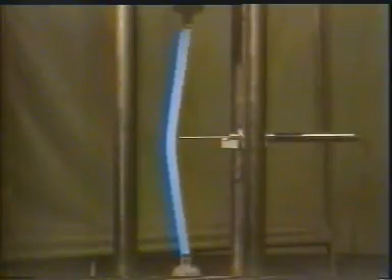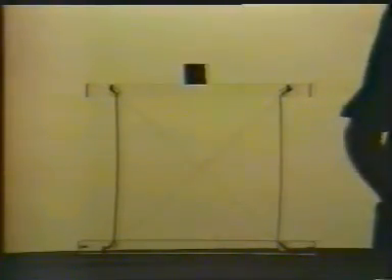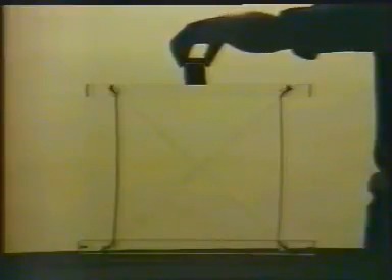A single half-wave mode is only achieved for an elastic column when the ends are free to rotate in the failure direction. In this test, a roller support provides such freedom. The resulting failure is a single half-wave. The effect can be more clearly seen on these slender columns.